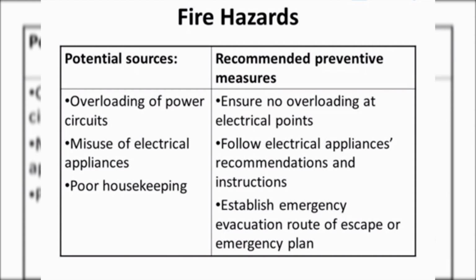Overloading of power circuits. Misuse of electrical appliances. Poor housekeeping. Ensure no overloading at electrical points. Follow electrical appliances recommendations and instructions. Establish emergency evacuation route of escape or emergency plan.